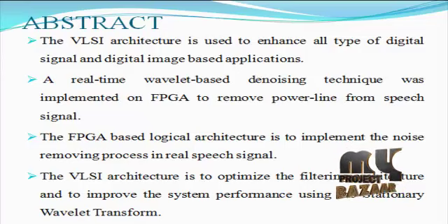The wavelet approach is applied to further reduce the noise by expanding the series of implicitly filtered shift invariant wavelet packet basis vectors. The implicit filter operation allows reducing the correlated noise while retaining low-level, high-frequency spectral components that are necessary for intelligible speech compensation for sensorineural impairments.